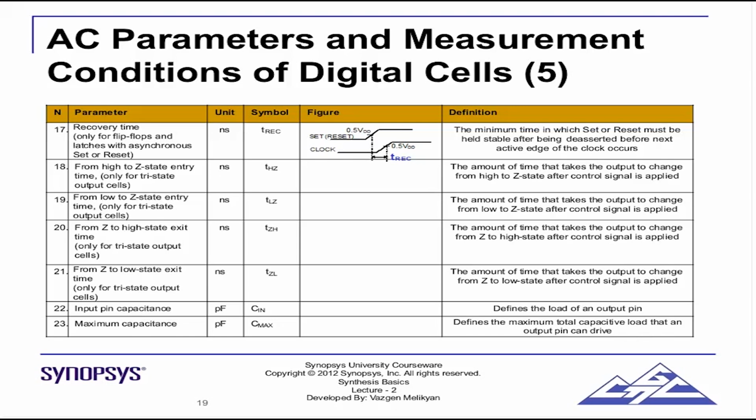Apart from propagation delay, the difference between combinational and sequential from a timing point of view is that sequential elements have timing constraints. They have timing checks built into them. So we have to make sure that our design, after being laid out properly, after the placement is done, meets these timing constraints for all the sequential elements in the design. And this is what static timing analysis is all about. It's a big subject that will come further.